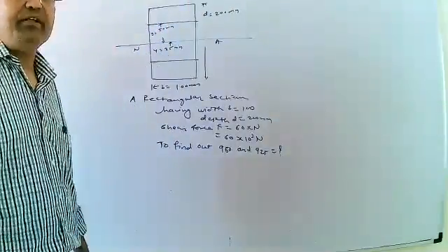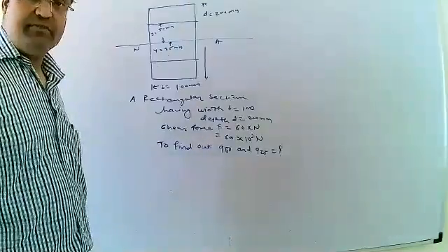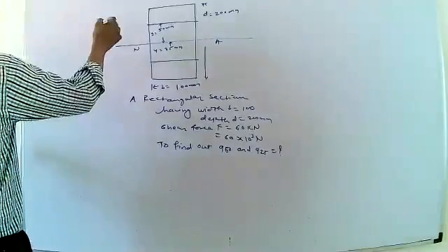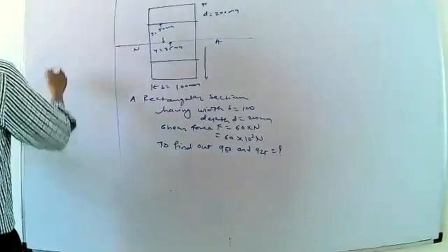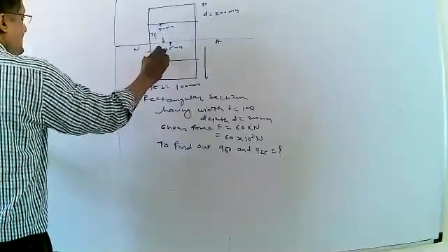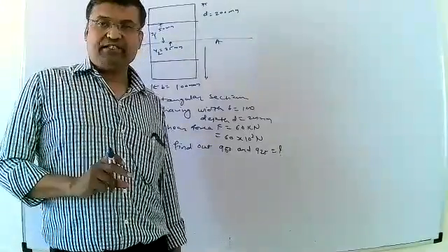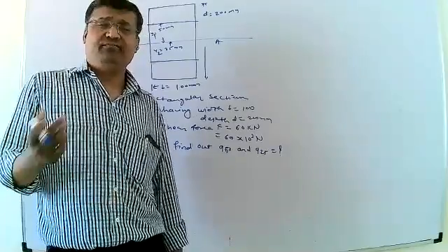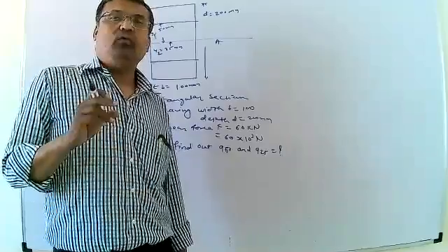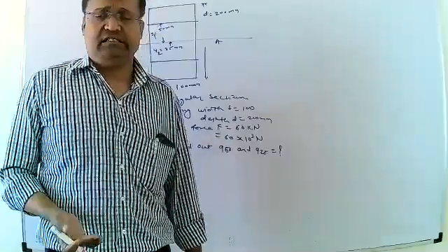It is a very simple way to calculate q50 and q25. The procedure will be the same as in the previous problem we already saw. Here the distance is represented; consider y1 and y2 about the neutral axis. For our sake of convenience, you just consider y1 as 50 mm above the neutral axis, and y2 as 25 mm below the neutral axis.